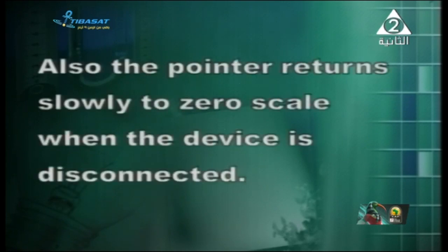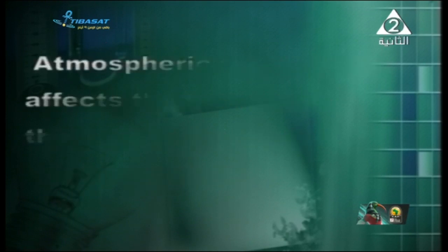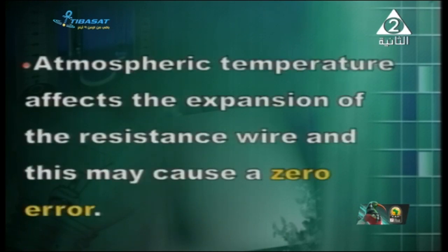Also, the pointer returns slowly to zero scale when the device is disconnected. Atmospheric temperature, meaning the temperature of the surroundings, affects the expansion of the resistance wire, and this may cause a zero error.